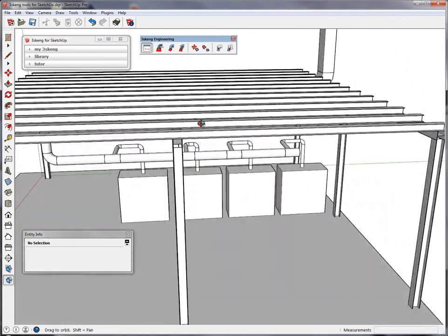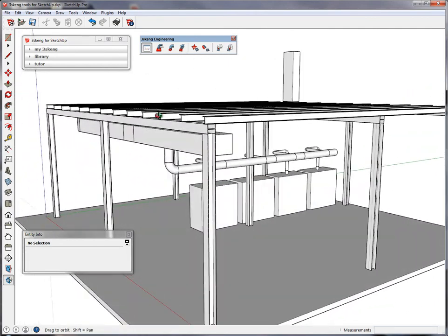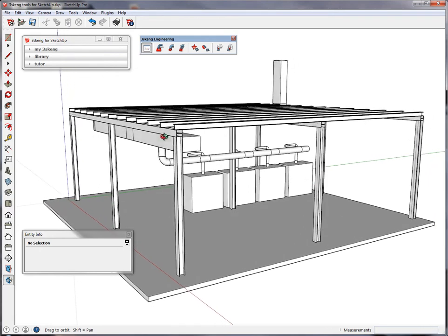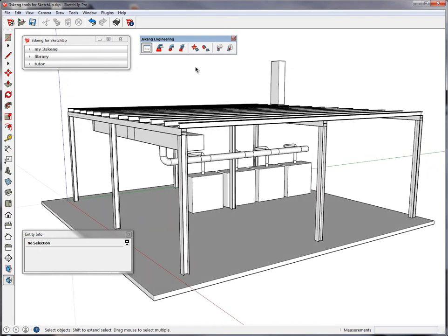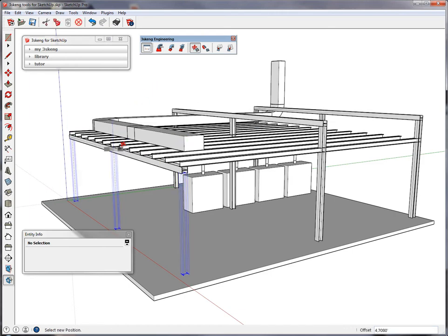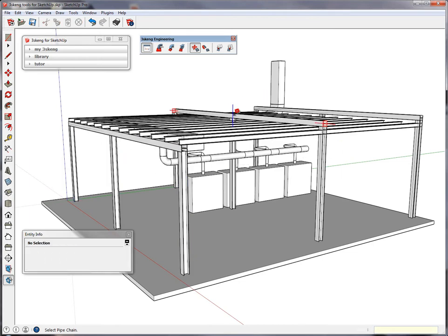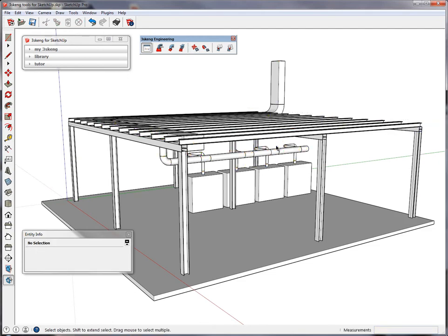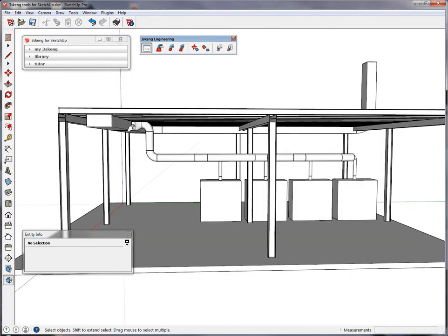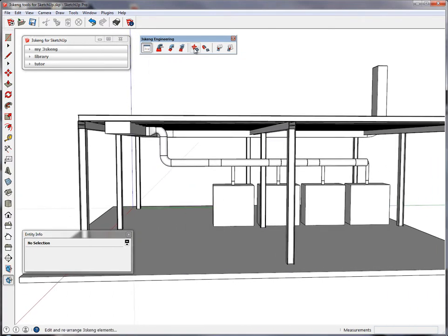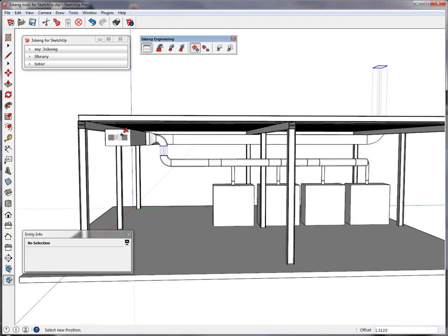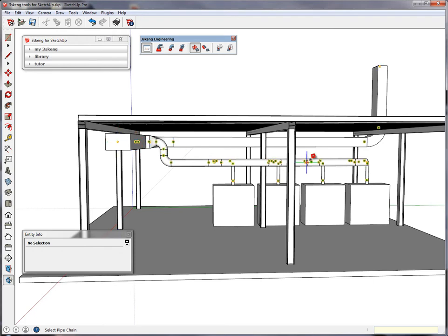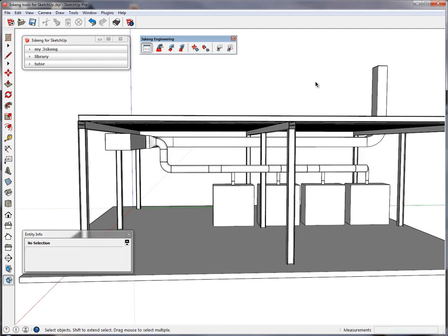It sometimes happens that in your project some parameters change. In this case, we got notice that the height of the building has to be reduced by 2 feet. We use the edit tool on our Steelwork and lower it by 2 feet. And see now that we have a lot of trouble with our exhaust. But if you use 3skeng, as you can see now, this is not really a big problem. So we can adjust the height very easy and fast.